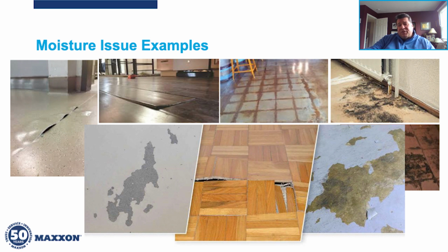And then you have some surfaces there that show an epoxy coating or even a paint over the surface of that floor, where things are starting to peel from excessive moisture coming up from the slab. And then you see a couple of pictures where we're showing mold and mildew that can grow because of the excessive moisture. So situations like this lead to certain outcomes.